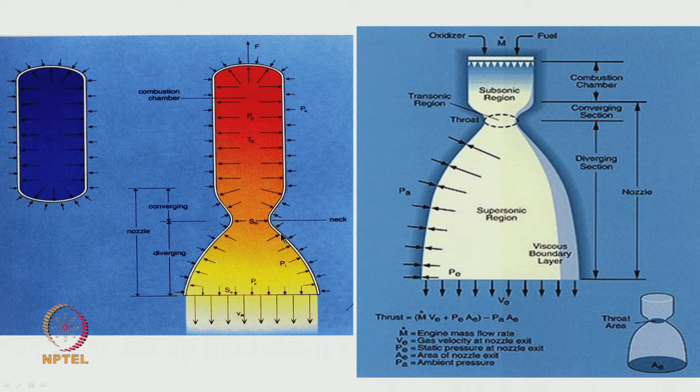So the net force, if you take a small element here or here or here, anywhere, if you take a small element of metal or wall here, the net force exerted on this wall is actually due to the difference in pressure across. So this minus this pressure times the area is the net force that is acting on the metal wall. This is an extremely subtle concept. Notice that I can redraw this picture by simply subtracting this arrow from this arrow and then removing everything here and then redrawing the picture.